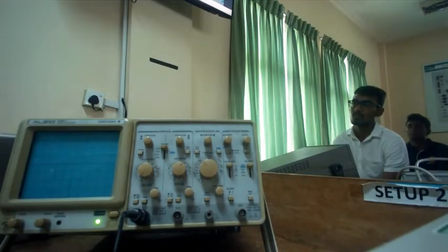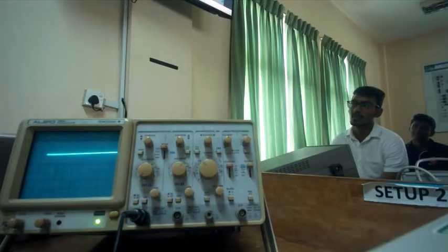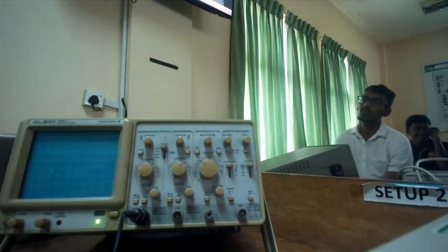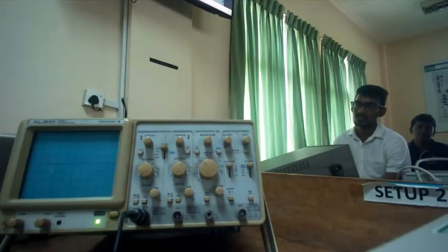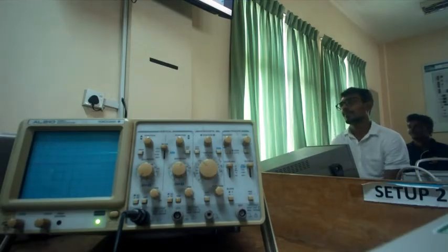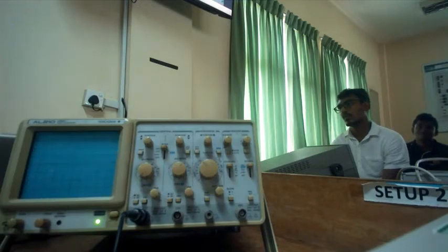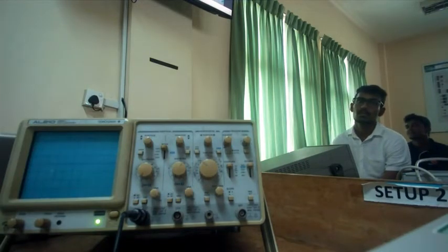Say 1/10 is equal to R1 over R1 plus R2. R1 is 1 mega ohm. So therefore 1 mega ohm plus R2 is equal to 10 mega ohms. R2 is equal to 9 mega ohms. Is that hard? Actually, you don't have to do all this math. It's voltage division, I think you should know intuitively. If I put R1 equal to 1 and R2 equal to 9, whether it is mega, kilo or whatever, that ratio is all that matters. And you will get 1/10. So this is basically what you have there.